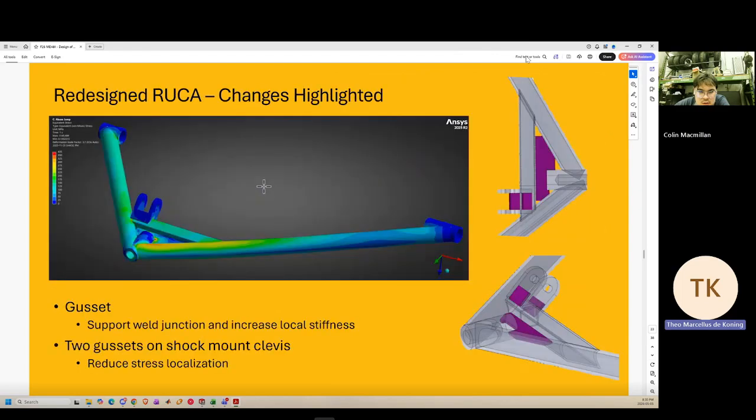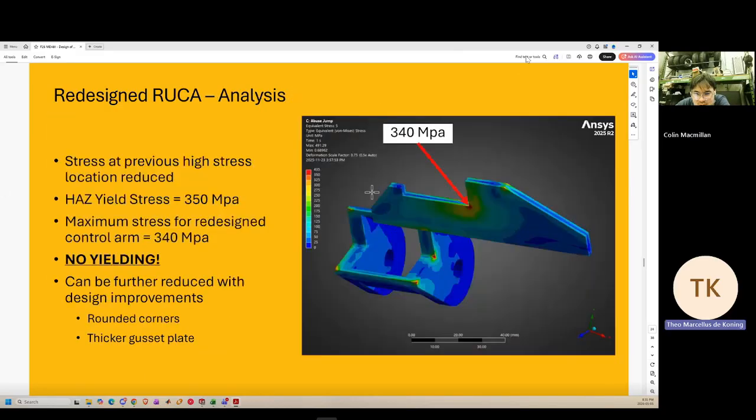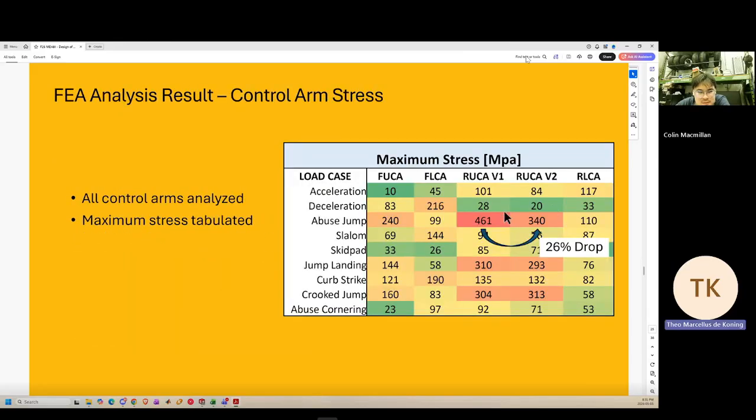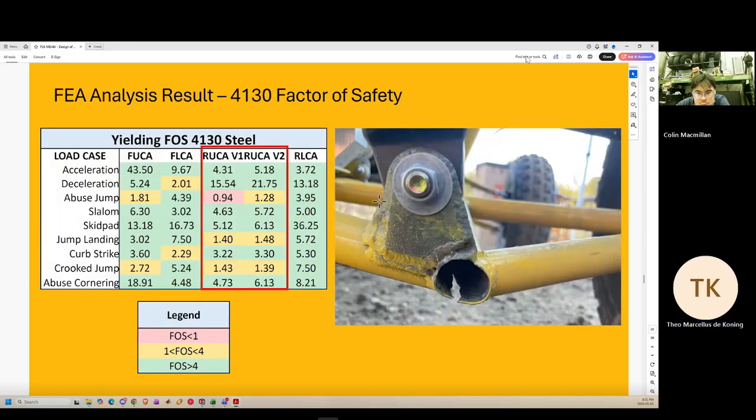These are all videos, which kind of sucks. I should have pulled it off. Anyways, to help prevent the super high stresses along all the welds, we put in this gusset. In reality, we didn't actually make this gusset. This purple one here. Okay. So hopefully it doesn't break. Anyways, made some changes. That gusset made it 26% better. This is factors of safety for each load case. So we get 16s on some of them, and then your lowest is 1 point something.